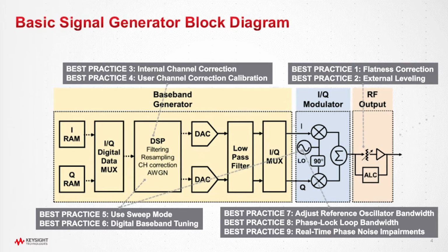Common signal generators are optimized for general purpose signal generation. Output performance of a signal generator is an optimized balance between measurement accuracy and speed. But nothing is immutable. Test signals can be high output power level or low output power level, wide bandwidth or narrow bandwidth, very clean or noisy, CW continuous wave or modulated signal, and burst or non-burst signals. You need to know how to optimize your signal generator for specific test applications.